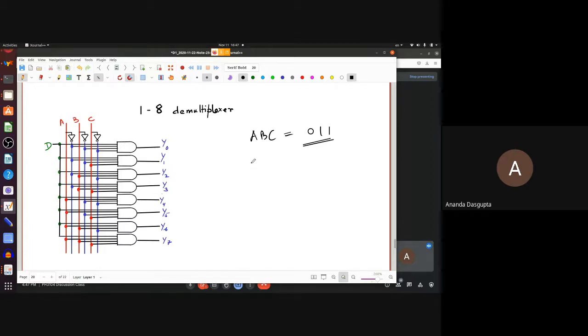Actually, what we are using here is this rather important Boolean result, which looks like a trivial thing to say if you think of dot as multiplication, but which it really isn't. A and 1 is the same as A always. If one input of an AND gate, or 3 inputs of a 4 input AND gate, are all 1, then the output is just the other input, for the simple reason that whatever the other input is, that will be the output. If the other input is high, the output will be high. If the other input is low, the output will be low. End of story. So A and 1 is always A.